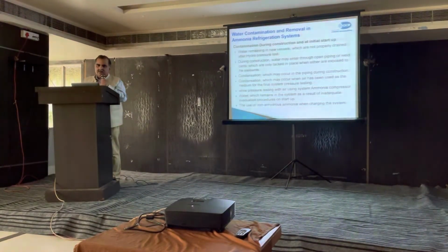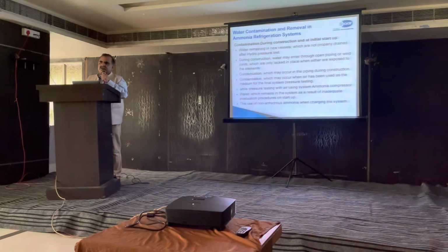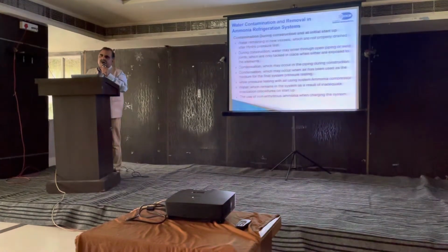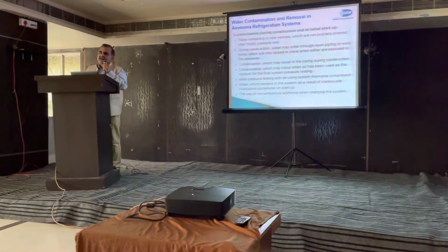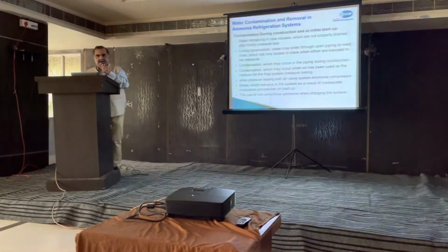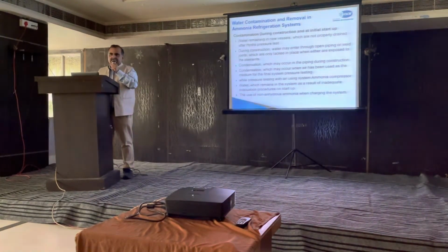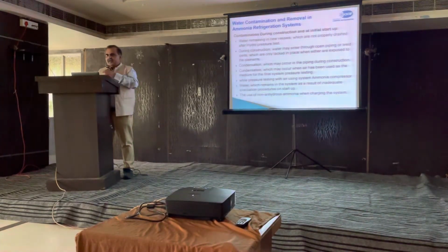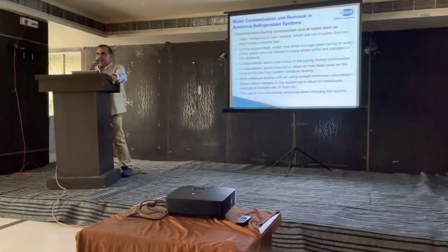When a plant is being installed and commissioned on site, many manufacturers do hydro testing. We as AR do not recommend hydro testing. We recommend that all the pressure equipment must be pressure tested using dry nitrogen. But unfortunately, dry nitrogen costs some money, so many manufacturers prefer to use hydro testing. Hydro testing means they are charging water into the vessels, and that water is not completely drained. So it is possible that water will remain in the pressure vessel itself. That's one big way of getting water into the system.